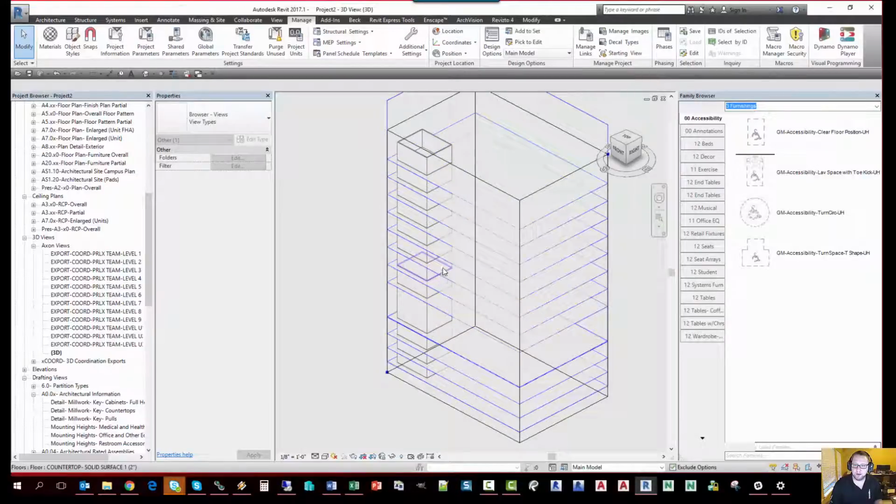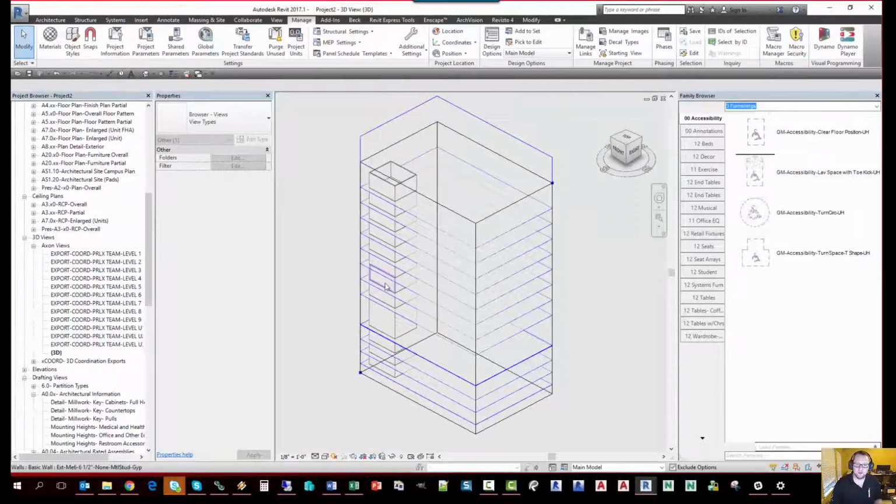At this point, your model may display in kind of a strange fashion where you may see some blue artifacts surrounding the model. This is only going to last until you've closed the model and reopen it, and it's only going to exist for the person who actually ran the Dynamo graph. But at this point, I'll save the model, close it, and then reopen it.